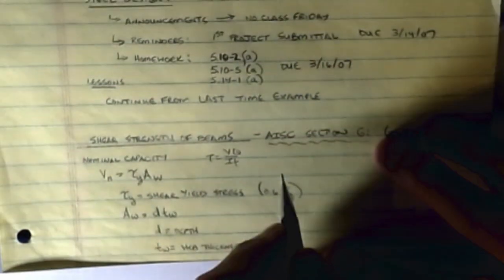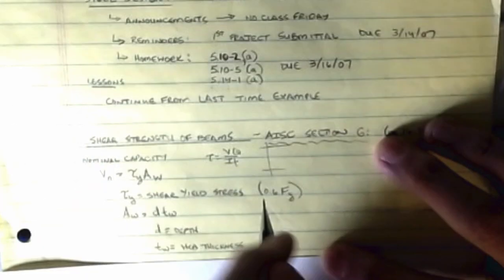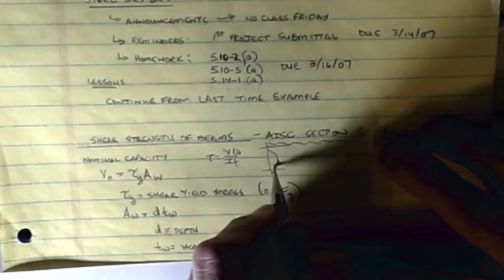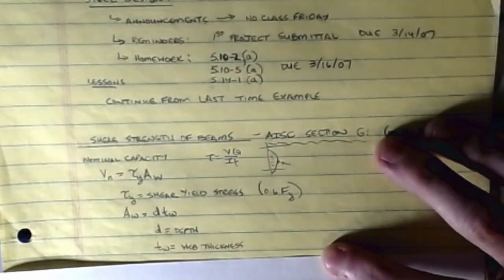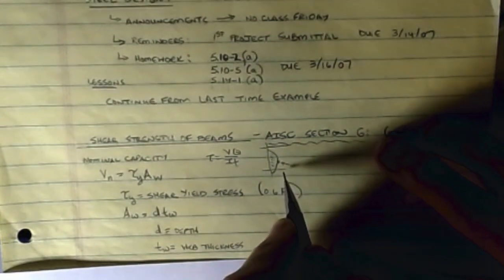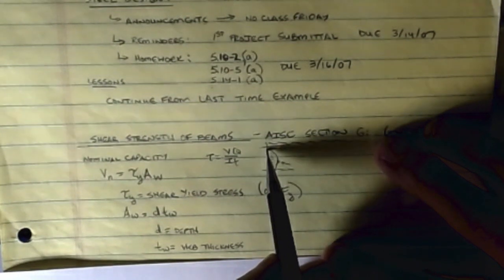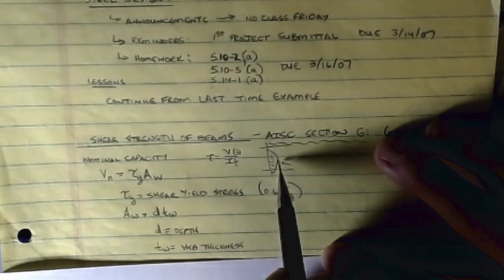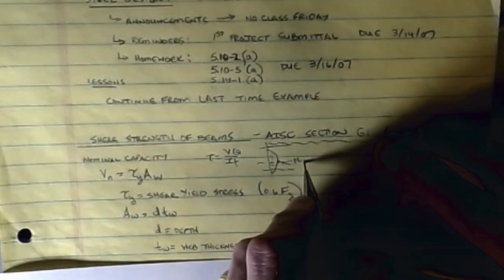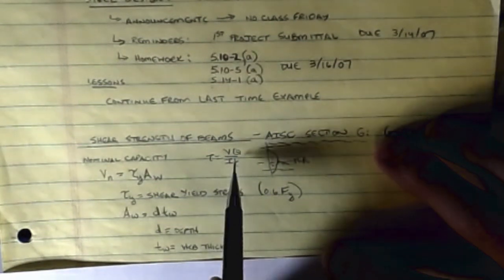And what that produced, for a rectangular section, was some sort of shear stress distribution that looked something kind of like this, in which the tau max was right there in the middle. We've talked about this in some of our other classes and lectures, where you had a tau of 0 at the top, a tau of 0 at the bottom, but this tau max always lived here, kind of at the neutral axis. That's the real mechanics approximation.